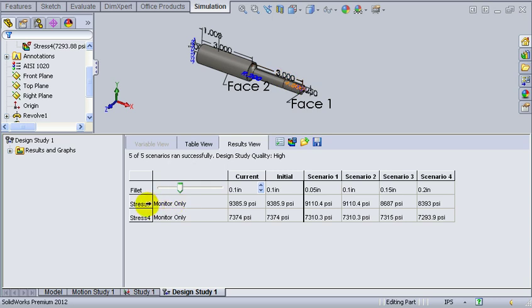So apparently you can see that the first scenario, right, has the maximum von Mises stress because the fillet radius is smallest, and then the second scenario, right, is smaller, and so on, right? So the stress number 4 location is approximately the same. Yeah, the first 2 scenarios don't make much difference. Yeah, that's interesting. So anyhow, that absolutely conforms with the observation from the table, right?